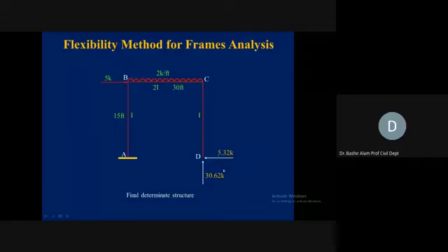The vertical reaction will be 30.62, it is upward, and 2 times 30, 60 in the downward direction. Means here the reaction will be in the upward direction to balance this 60. We already have this 30.62. So it will become 29.38. This will be the vertical reaction.